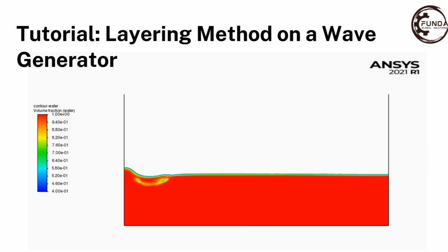In this demonstration, the piston-like boundary moves back and forth, and Fluent uses dynamic mesh layering plus VOF to generate accurate periodic waves inside a multi-phase domain.